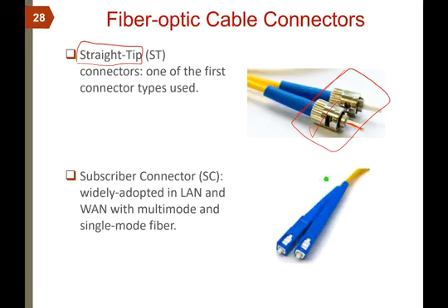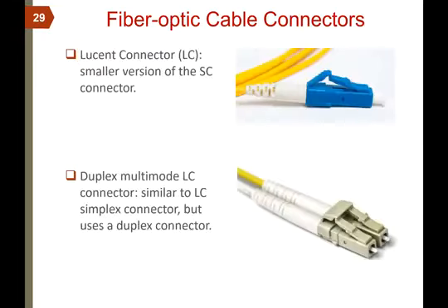Subscriber connector, nowadays these are used most widely in LAN and WAN with multi-mode and single mode. So we use these both for multi-mode and single mode. This is actually glass, but it's not the glass or the fiber from the cable, because here the connection will happen. You have to properly terminate these.